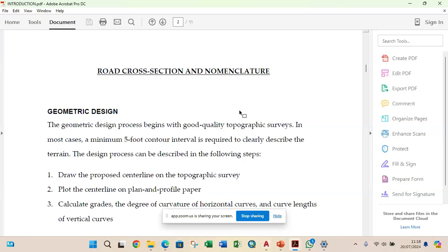They will know the vehicles that apply that route. So based on what they've done in the highway manual, they specify that the minimum thickness from the subgrade to the finished level should be 500 mm, that is 50 cm thickness. Your sub-base 200, the base 200, then the wearing and binder 40-40, 60-40.